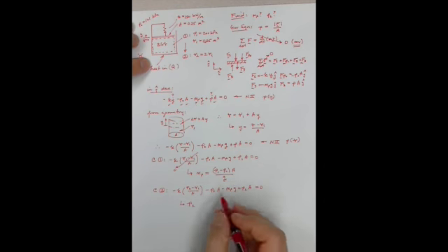So P2 in this case is going to be equal to P naught plus the mass of the piston, gravity, over area. And then I have to divide through by A here. It's going to be plus K times quantity V2 minus V1 over A squared.